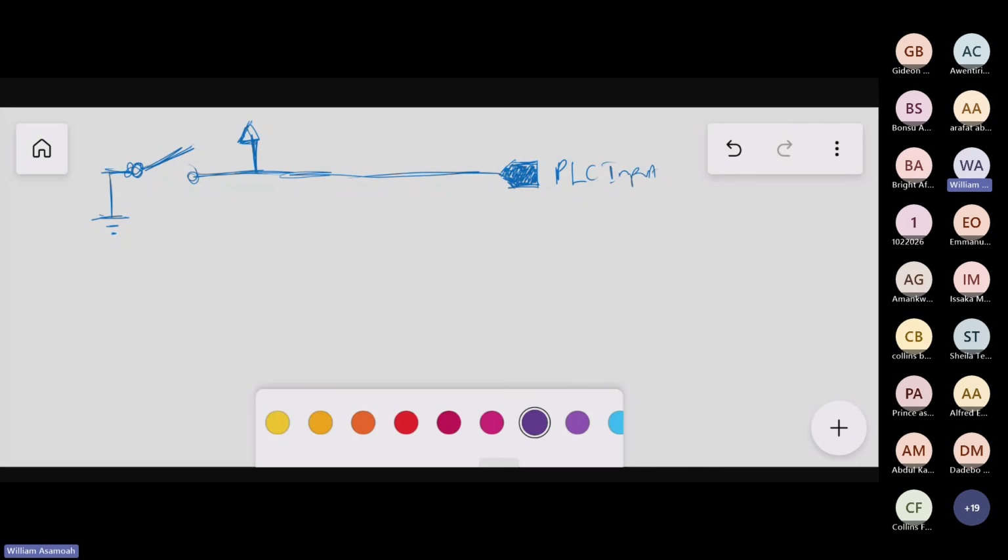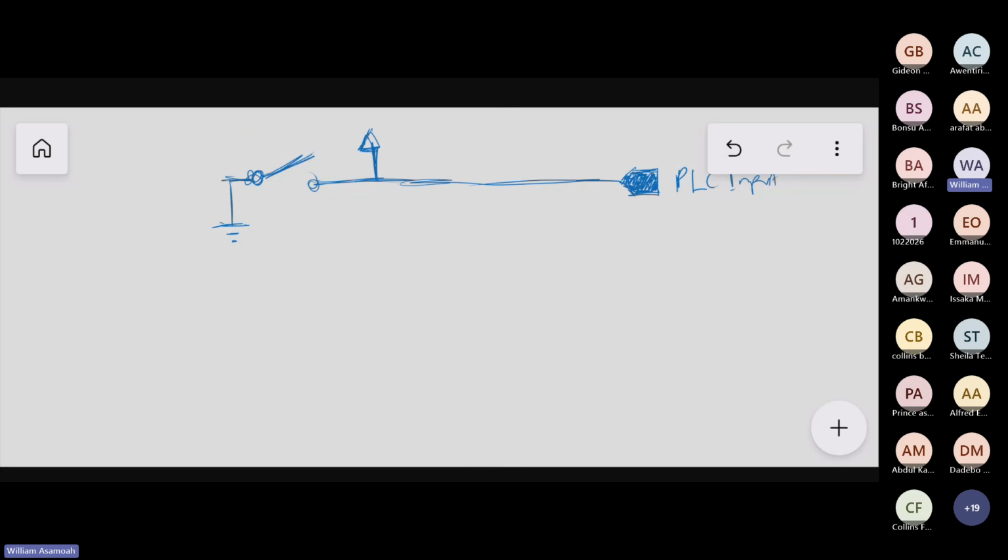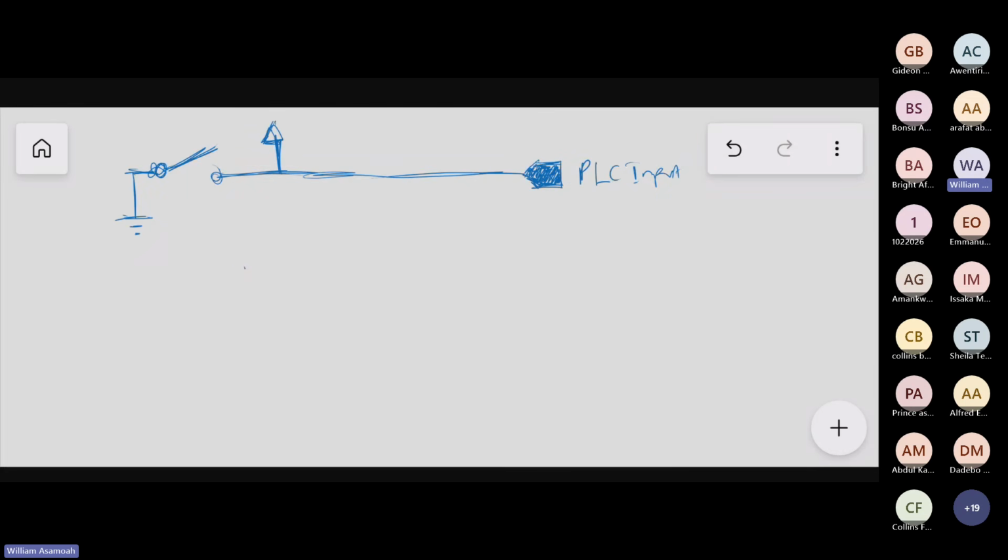This one is getting a little bit electrical, more technical. Let's look at what happens here. If I have a switch like this, we've done parallel connections. Then this one goes to ground. And I'm connecting this to an input. And this one is 24 volt. You can say that this voltage is already connected to high.